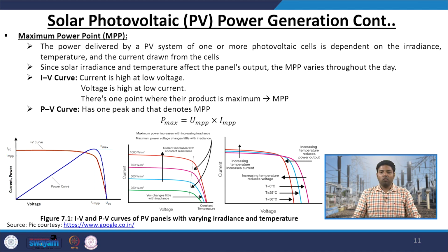Now always we want maximum power from our PV panel, we do not want to operate at a lesser power. So, how to get the maximum power? A PV panel has a typical characteristic that if you increase the voltage level, that means you are creating more and more free electrons and holes. So, if your concentration becomes very high, their chance of recombining with themselves becomes very high. If that is the case, then your current at the output level will start falling. So, you have less current in your circuit.